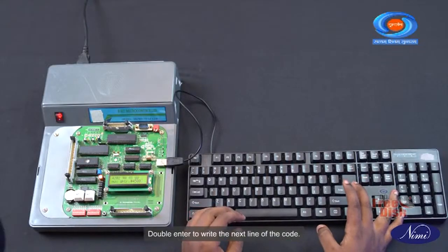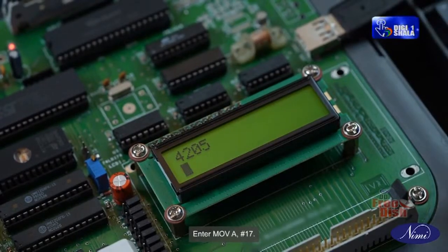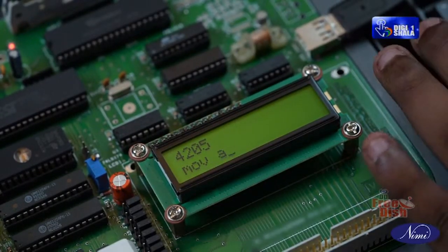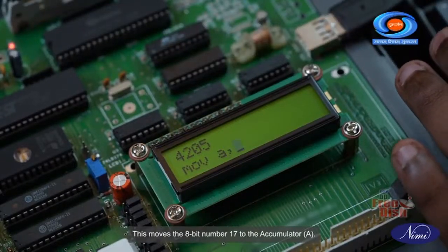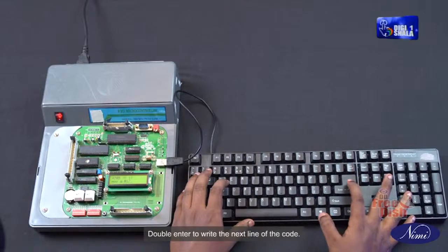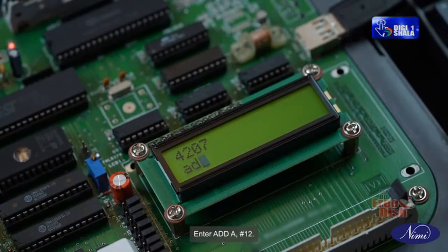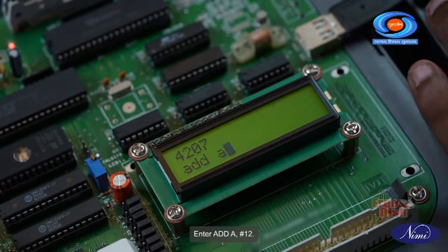Double enter to write the next line of the code. Enter MOV A, #17. This moves the 8-bit number 17 to the accumulator A. Double enter to write the next line of the code. Enter ADD A, #12.